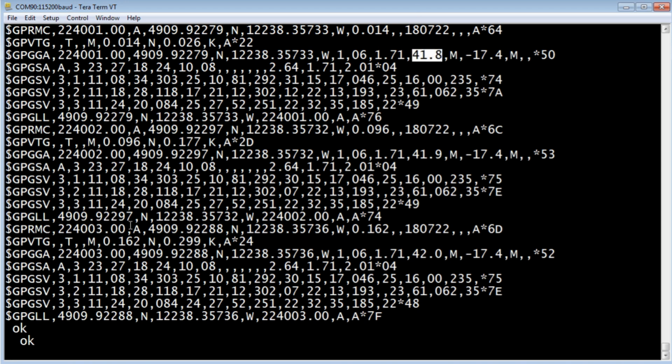So if we look down at our GPRMC, which is down here, same thing. There's our time and our latitude, longitude. And right here, A means active. It's not V anymore. Before it was V for void. Active means it sees enough satellites to give us some information. So we could now parse out the data because we know the fields.